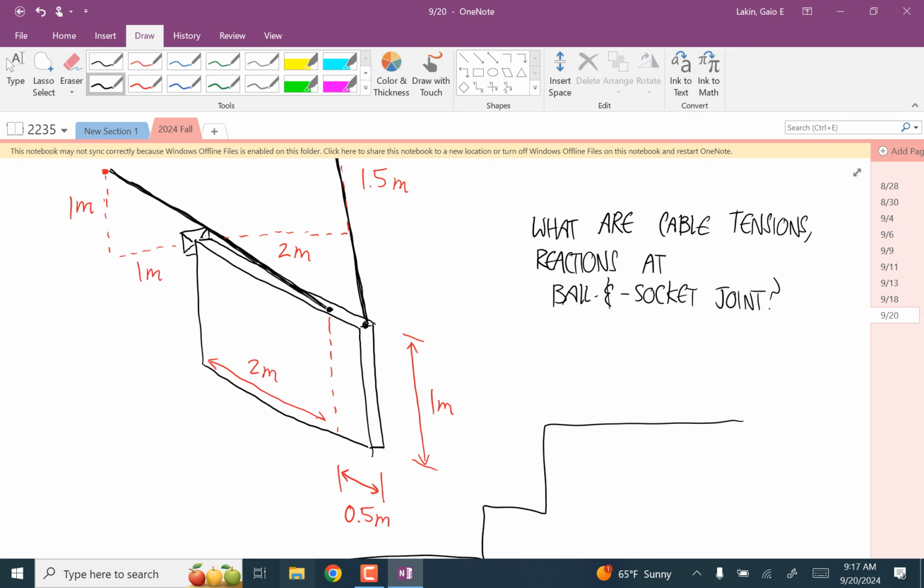And now think about rotations. Can it rotate about like this is a paddle? Can it rotate that way? Yeah, so there's no couple there. Can it rotate like a hatchet? Yeah, and then can it rotate flop side to side like a fish? Yeah, all those rotations are still allowed. And so this is only going to apply 3 components of force. Okay. What was the mass? 50 kilograms.